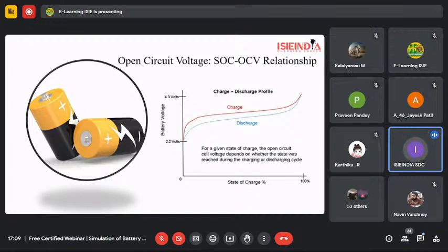And most of the time, the standard is 3.7 volts. It is the nominal voltage; most of the time the battery will be on its 3.7 volts. So this is the nominal voltage, the upper voltage, and the lower voltage. This one can be the lower cutoff voltage, and this one will be the upper cutoff voltage. If a battery exceeds this voltage, the battery may get damaged, or its potential may change, and the battery may blast or explode.